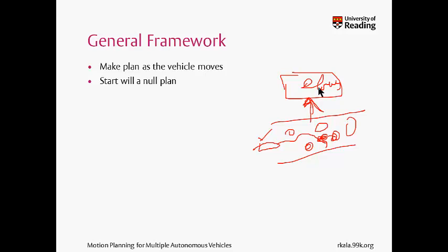It's immediate, at all times it is seeing what's happening. A new obstacle, it rectifies the plan. An obstacle went away, it rectifies the plan. It's rectifying the plan as the environment changes. The vehicle moves, now it's at a position here, it modifies the start point to this, and correspondingly the trajectory gets modified. The vehicle slipped, it forms this trajectory. So my planner is continuously looking at the environment and it's making the plans.